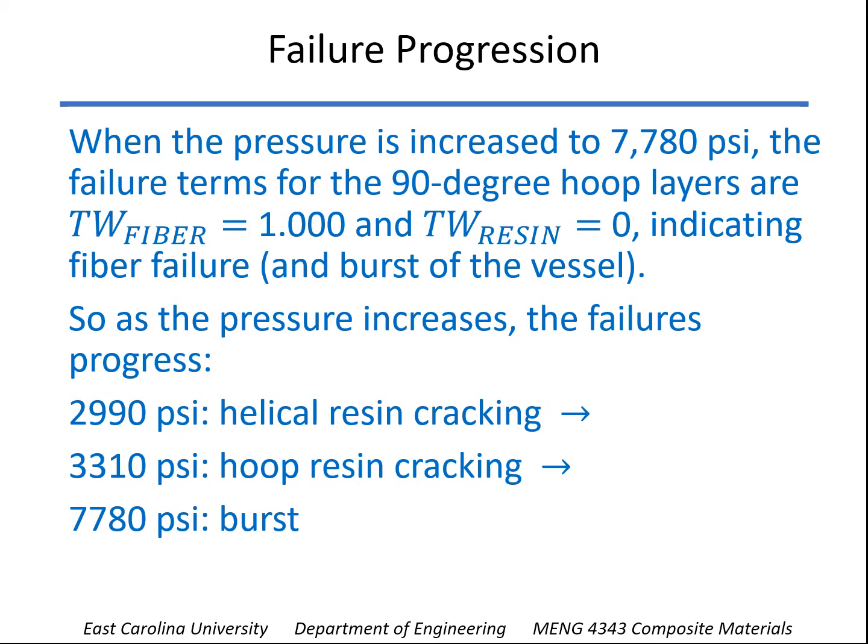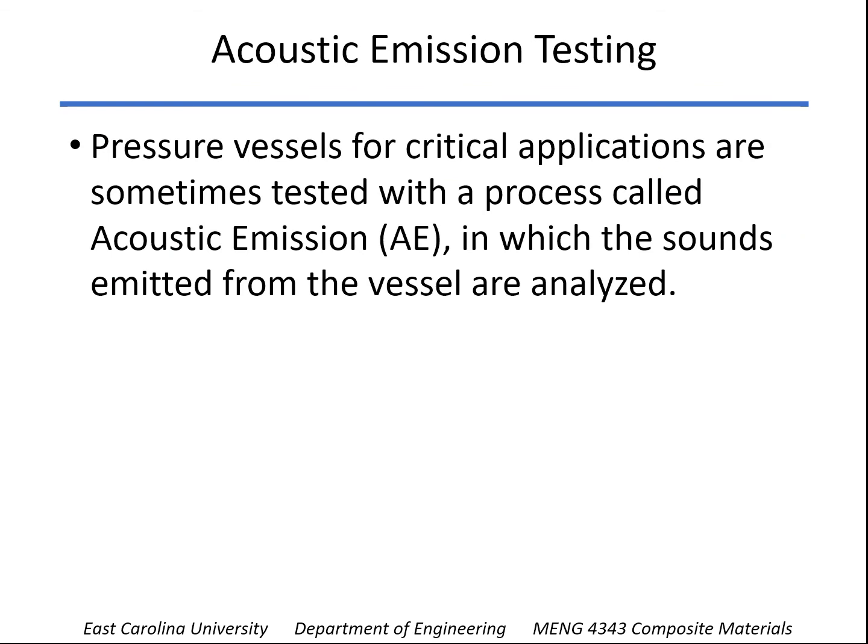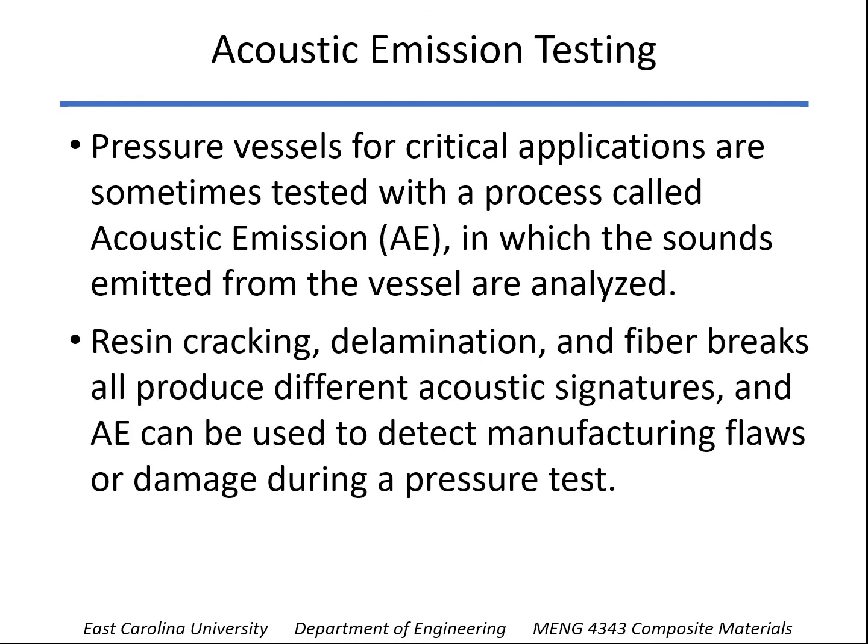Now I mentioned you hear the resin cracking. There's a process called acoustic emission testing. And if it's a critical application, a lot of times you'll evaluate the sounds that are being emitted from the vessel, because fiber breaks, delaminations, and resin cracking all have different acoustic signatures. And so sometimes you can detect manufacturing flaws, or if it's been in service for a while, accumulated damage during a pressure test.